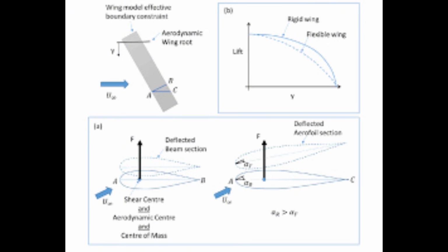Flight control systems also evolved in response. Swept wings altered stall behaviour and roll response, especially at high angles of attack. Engineers introduced new control strategies, differential spoilers, and refined aileron designs to maintain handling quality. Later, these challenges accelerated the adoption of powered controls and stability augmentation systems. The path toward fly-by-wire began with problems introduced by high-speed aerodynamics.